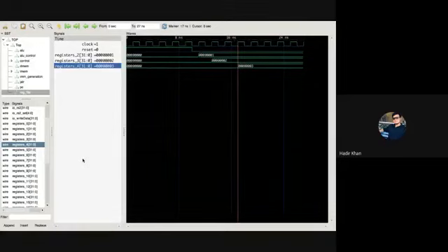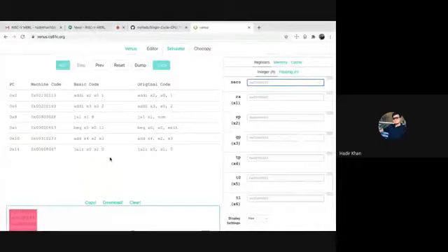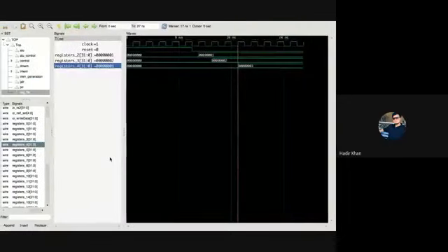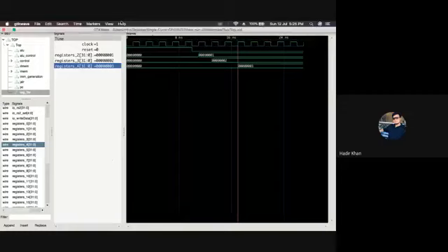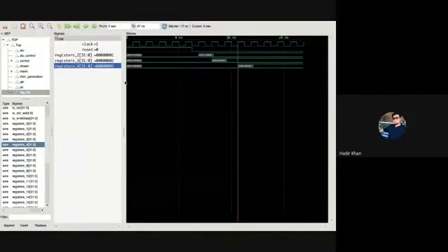of how you can simulate your processor using Venus. You can write basic programs, then you can generate the hex code of it. You can basically write it in your processor by giving the file path in the InstructionMem.scala file, and then you can generate the VCD file using Verilator. You can have a quick look if everything is working fine using GTKWave. And by the way, this is another open source tool which uses the VCD file to basically see what's happening inside the processor.